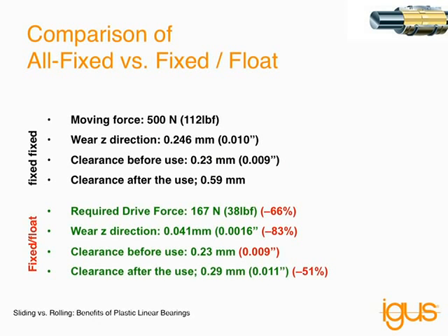Now this is the really cool part. I really like to show engineers who are skeptical about the use of floating bearings the benefit when I'm visiting them. Because a lot of people, and it's kind of common sense, think that by introducing a set of bearings that has enhanced clearance you're going to increase the clearance in the whole system, when in fact it's not really like that. That fixed bearing side will define the precision of the system.